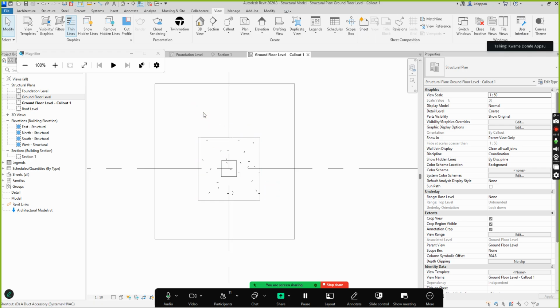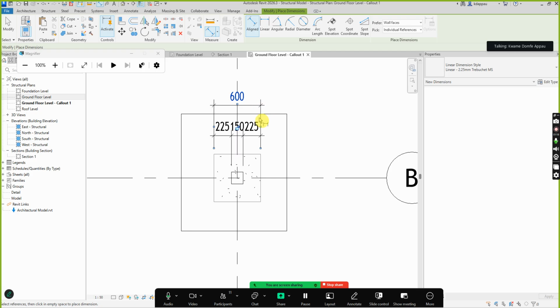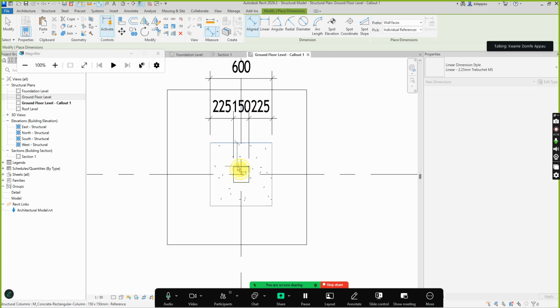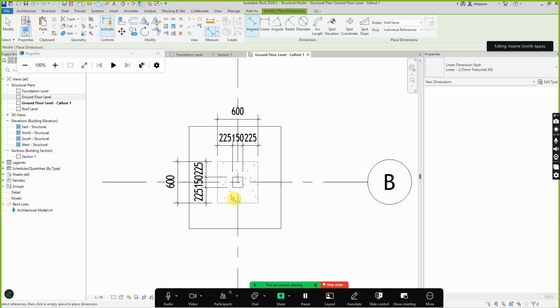I can then dimension it, DI, from here to here to here to there. So I have this dimension. I can then do the overall dimension to get this one, as is done in structures. I can come and do dimension from here to here to there, then bring it here. Then I can do the overall dimension from here to here. The process of dimensioning them, adding text to them, doing whatever to them is called annotation.